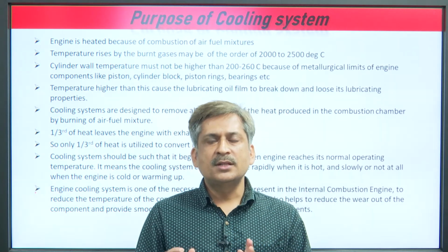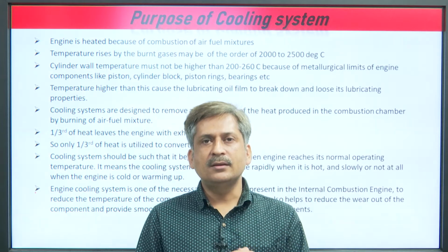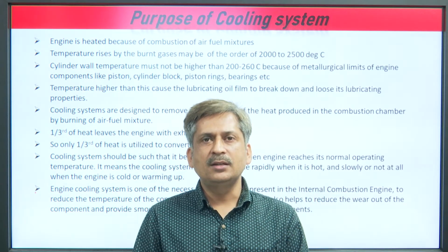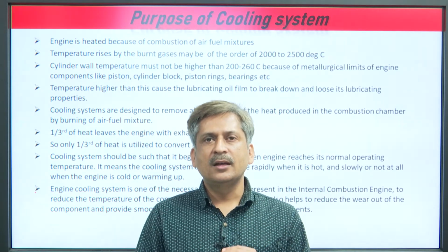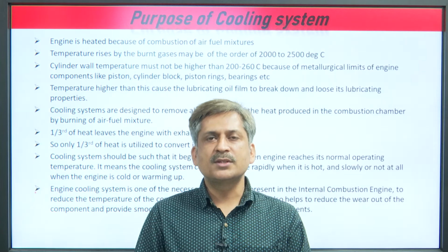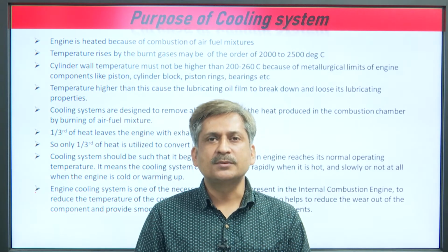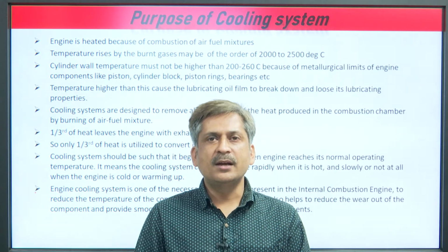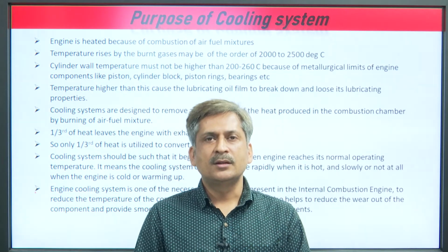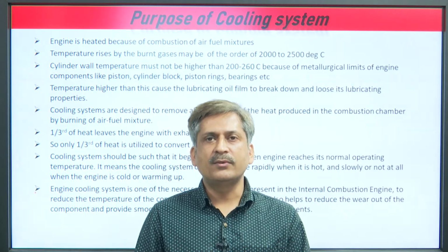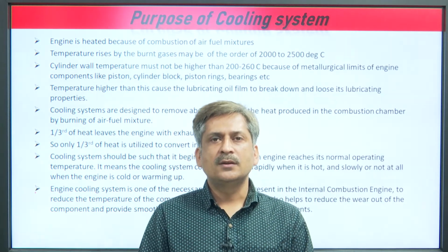This temperature rise affects in two ways. First, it disturbs the metallurgical limits of the engine components, and second, it breaks the lubricating oil films, which are required for smooth engine operation, like in bearings and different components of the engine, where we need some lubrication.